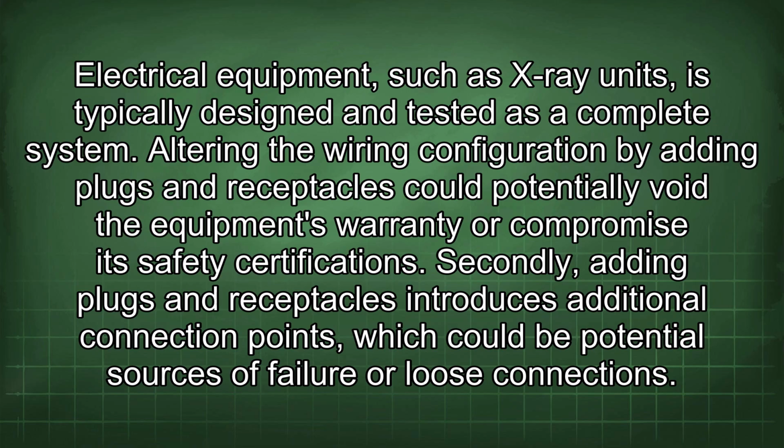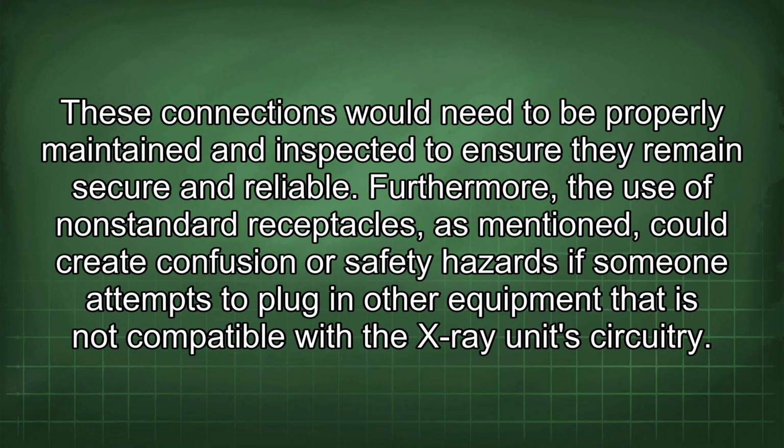Secondly, adding plugs and receptacles introduces additional connection points, which could be potential sources of failure or loose connections. These connections would need to be properly maintained and inspected to ensure they remain secure and reliable. Furthermore, the use of non-standard receptacles, as mentioned, could create confusion or safety hazards if someone attempts to plug in other equipment that is not compatible with the X-ray unit's circuitry.